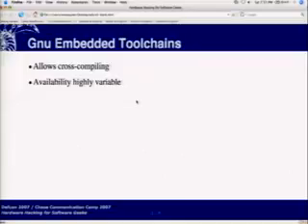Basically what you do is you have to compile a cross-compiler, which means you delve into the specifics of all the GCC compilation settings and pick your architecture to compile cross-compiled binaries for. What this allows you to do is, if I've got GCC that cross-compiles to ARM, I can make an ARM binary, load it onto an ARM chip, and have it run natively. That's very important because none of these microcontrollers will use the same instruction set as my x86 laptop here,